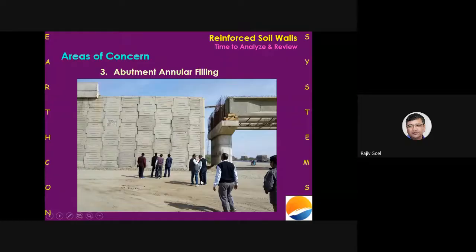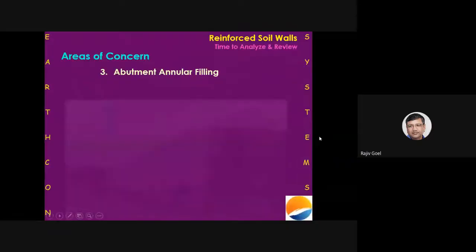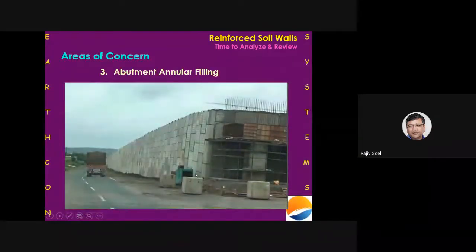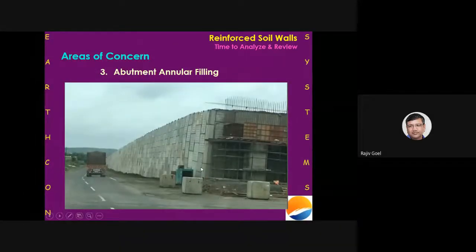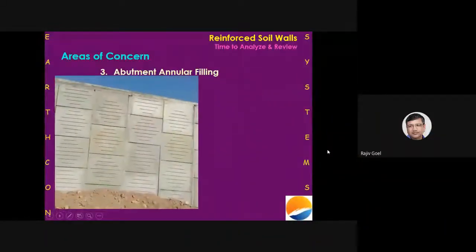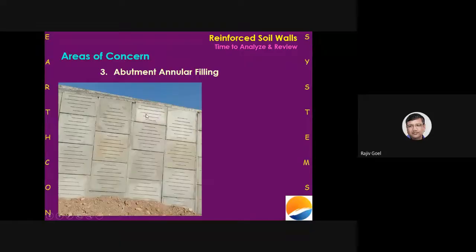And this was primarily because the backfilling in the open excavated part, which was excavated to put my foundations in, was not filled back properly. If you think this is not very visible, I'll show you one more slide, and I'm sure you can make it out very easily that these 4 panels here have actually sunk into the ground. Because of that, these gaps have opened up, and what we're trying to do here is fill this up with a lot of concrete.